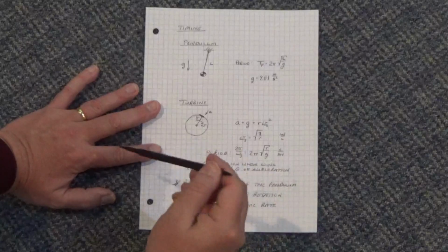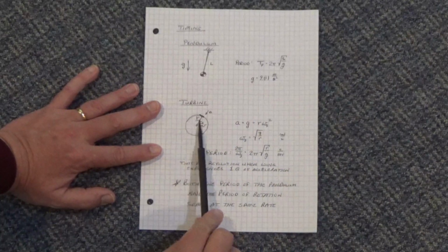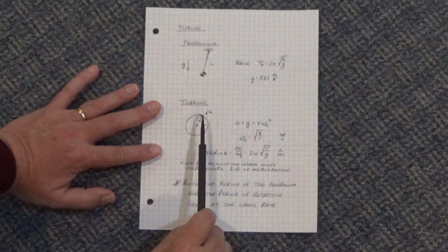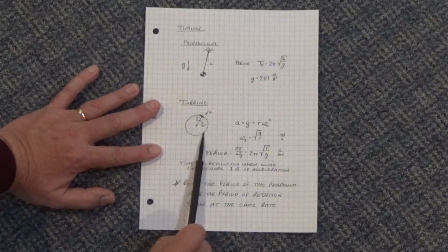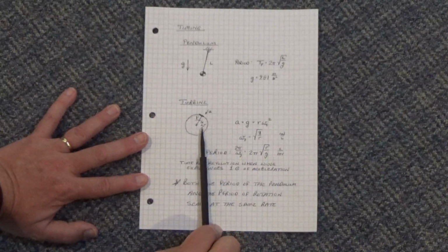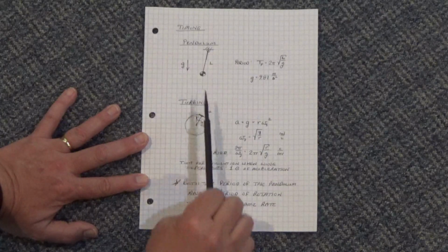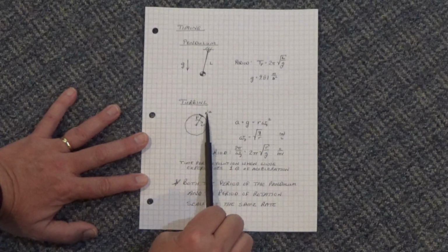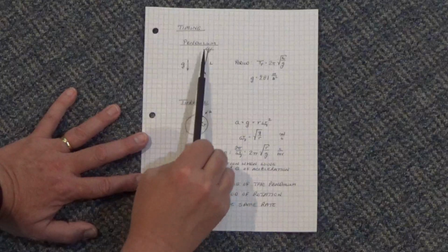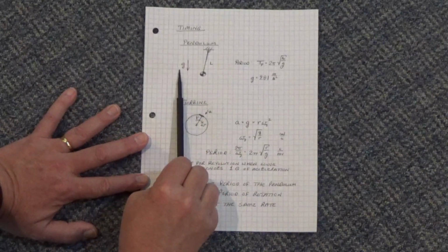Okay, we want to make sure that this pendulum can react fast enough, so we'd like it to be able to swing one way or the other within a rotation of the turbine, or preferably even faster than that. And so what speed we want to compare it to is when the turbine develops an acceleration that's equal to g. I mean, we test the period of a pendulum in a 1g field.